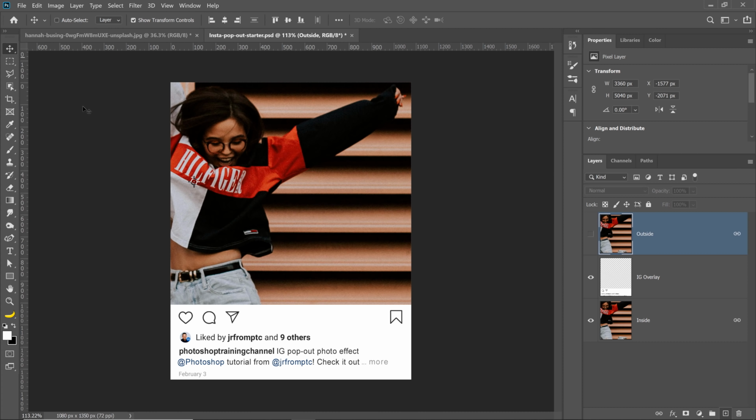And here's a quick tip for you. If you accidentally go into the vertical guides, but you wanted a horizontal guide, don't worry. All you need to do is hold Alt on Windows, Option on the Mac, and you'll flip it, and you can bring it down and place it where it needs to go. You don't need a perfect guide. I'm just using it for a quick visual reference.